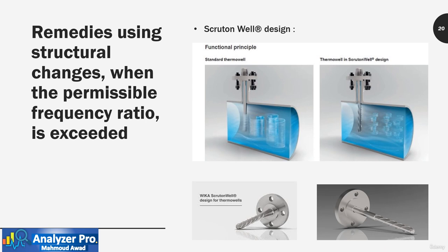Another better solution is the use of the screw-on well design. This design reduces the amplitude of oscillation by more than 90% compared to conventional probe designs. The design allows an easy and fast installation of the sample probe without expensive and time-consuming rework on site.